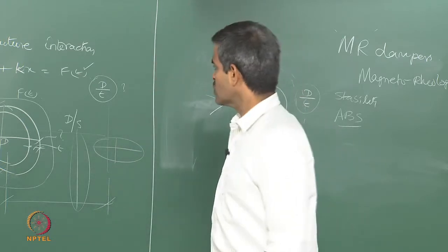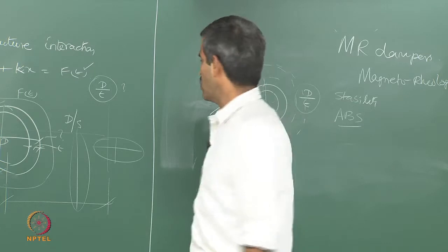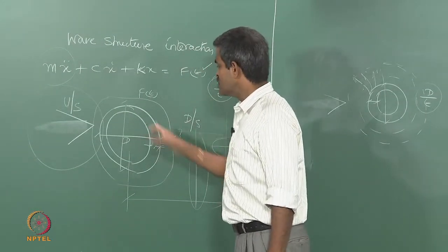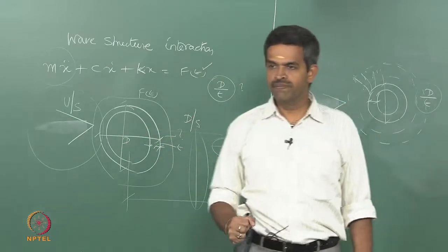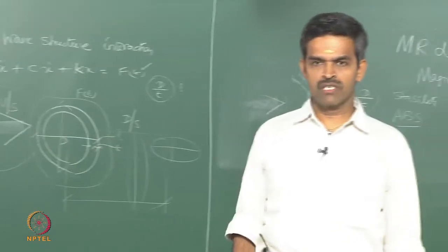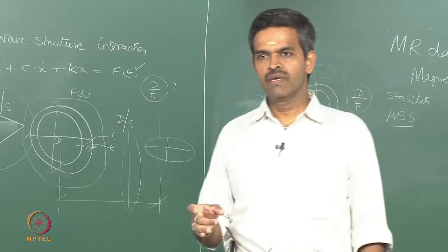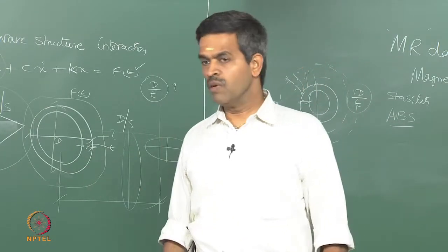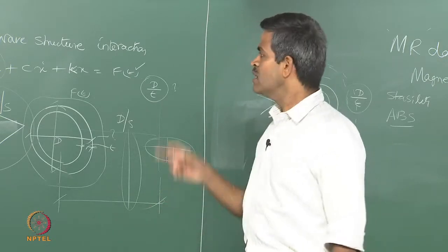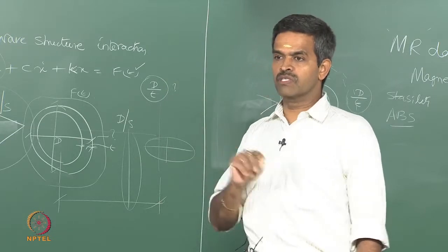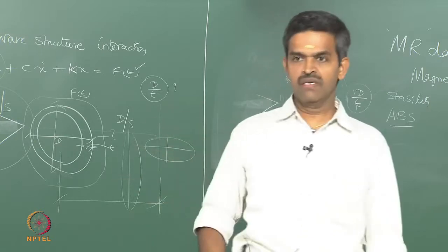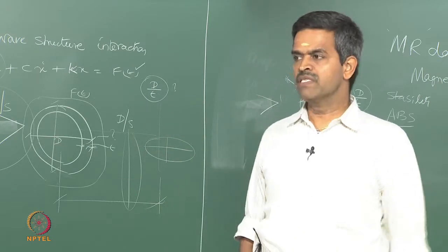So, if you are able to construct one more member, that is one of the important characteristic dimensions: how you place the spacing of the columns in a given TLP, or place the columns in a series of breakwater structures. What should be the spacing between the piles or the column members? You must always try to find out the distance beyond which the interference of the member, or fluid structure interaction, becomes nullified. Otherwise, it will cause secondary effects on the given member itself which will damage the member.